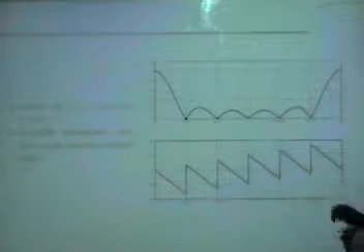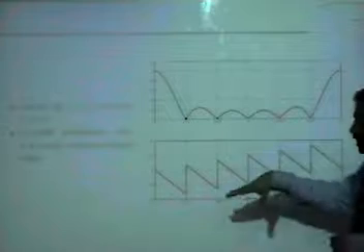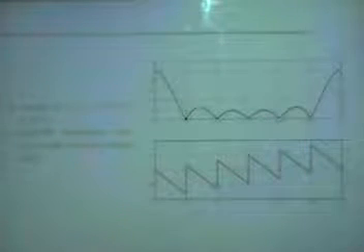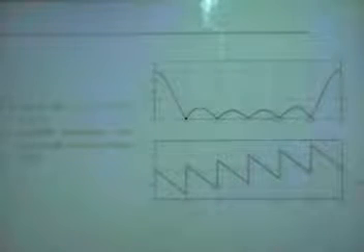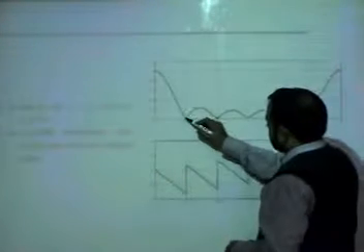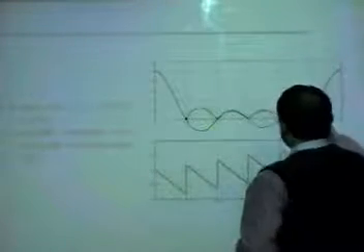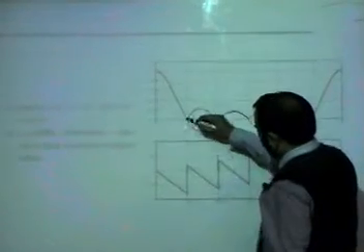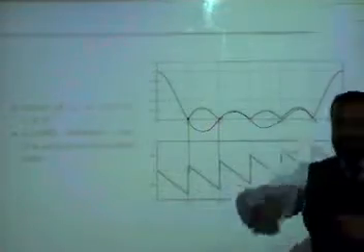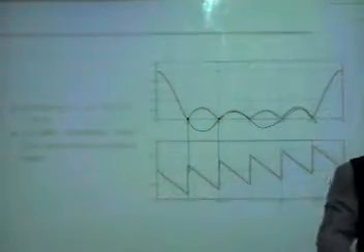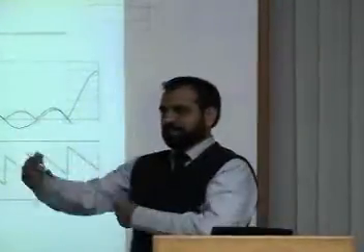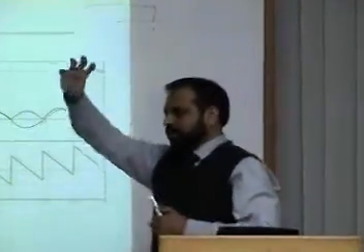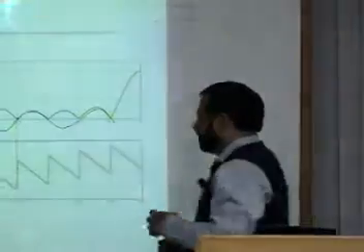And though the phase is linear, it appears broken. Why? Because you are plotting it from minus pi to pi. And secondly, wherever it crosses 0, there is a change. We say it is a 180 degrees phase change. Wherever your magnitude is crossing 0, it's a change in phase. If something is coming out positive, positive, positive, it will go negative. So that's why you see this.